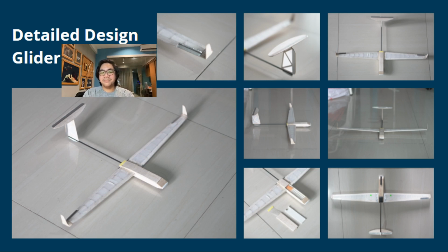Our glider is mostly made out of balsa wood, which is bound together using CA glue. For strength and rigidity, we are using carbon fiber rod for the tail boom. For any surfaces that might contact the ground, we are protecting them using EVA foam or bicycle inner tubes. The bicycle inner tube is used on the skid pads, and for additional friction, we have added the double-sided sticky tapes. And for the wings and tail, we are covering the balsa structure with covering tissue for aerodynamics and lightweight. And finally, for the control surfaces, we are using foil tapes.